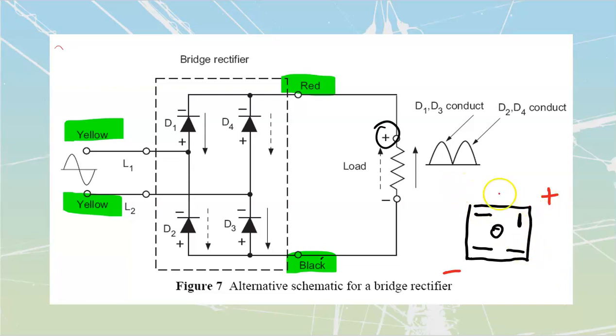Sometimes on the package, what you'll also have is a sine wave, and a plus and a negative. That's relatively easy for you to identify. The sine wave is going to be the AC. Connect any AC polarity onto it, right? Doesn't matter, your two lines go onto there, your positive and negative go over there.